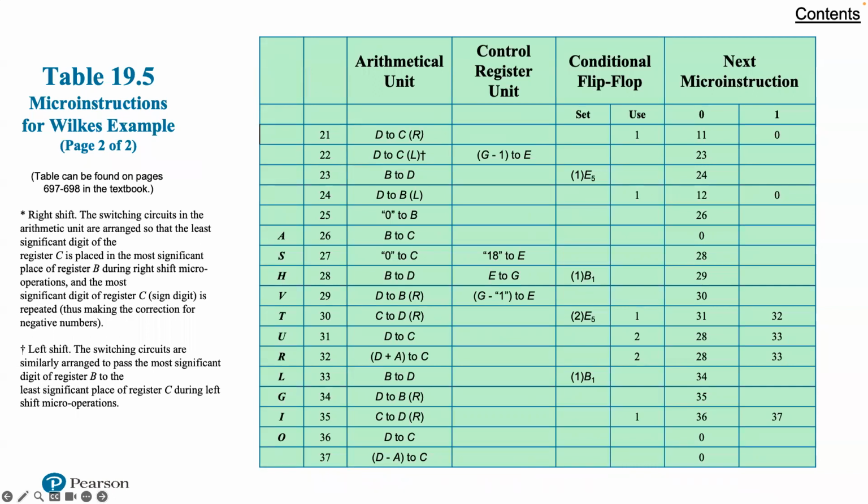The principal disadvantage of microprogrammed units is that it will be somewhat slower than a hardwired unit of comparable technology. Despite this, microprogramming is a dominant technique for the implementation of control units in pure CISC architectures due to the ease of implementation. RISC processors, with their simpler instruction formats, typically use hardwired control units.